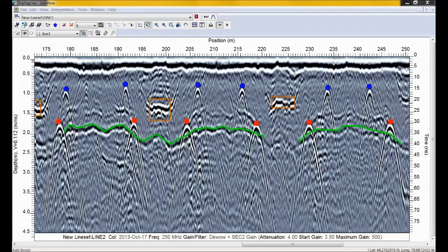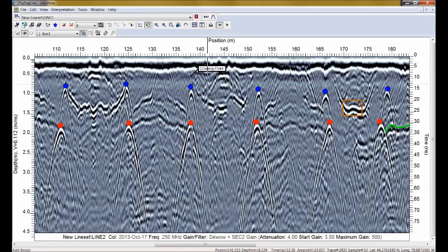Now, if I make annotation 1, I only have the one annotation. If I want to edit it, again, I can click on the finger pointing, click on it. It's now the active interpretation. Now, I can do a few things. You notice there's a couple handles on here. I can grab this handle, and that will move the annotation, but it will keep the point that it's pointing at in the same spot. I can also do the opposite. If I grab this one, I can change the position of that, and the annotation stays in the same spot.